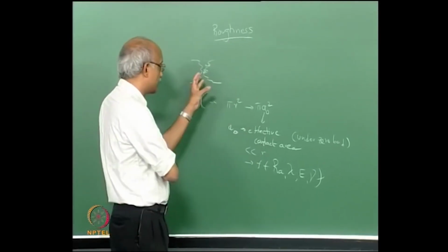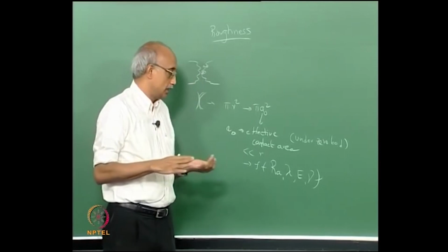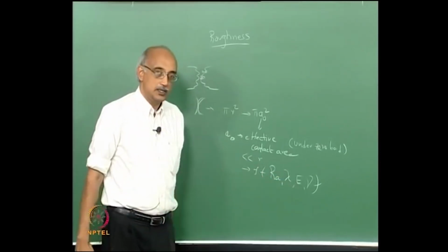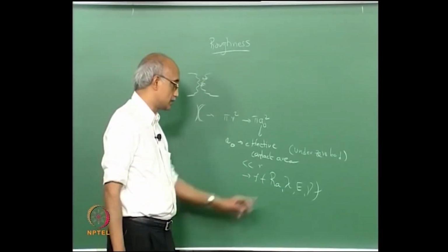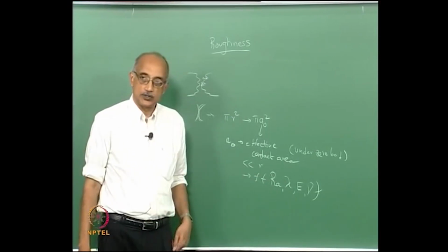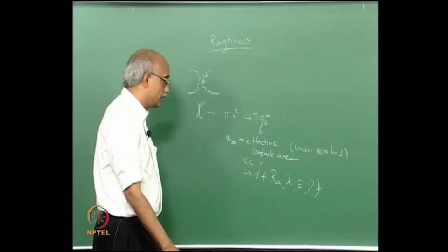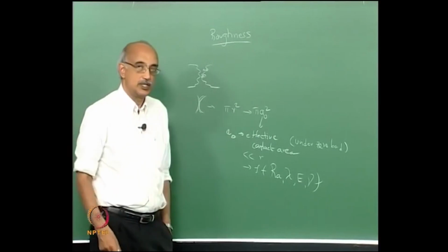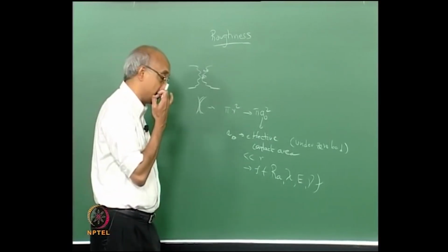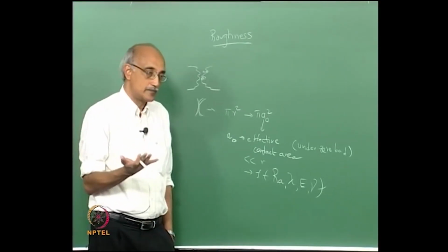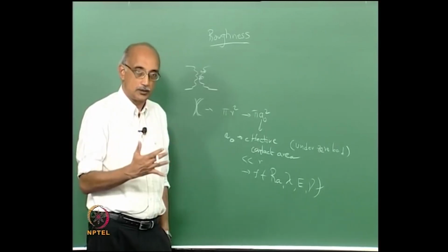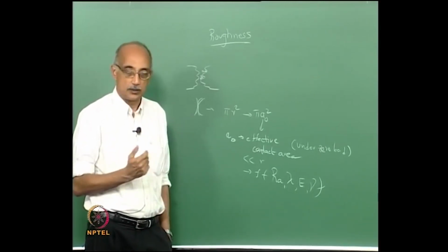And so, for the same roughness, depending on the values of E and nu, that is the Young's modulus and Poisson's ratio, you can get very different kinds of behavior in terms of whether the adhesion is effectively greater for a rough particle or lower for a rough particle.